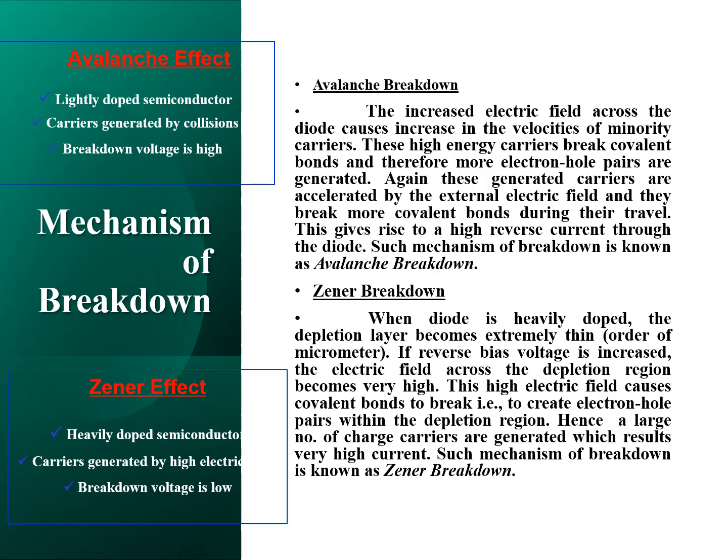In reverse bias, two types of breakdown occur: avalanche breakdown and Zener breakdown. What is avalanche breakdown? In reverse bias, whenever we increase the reverse voltage, the minority charge carriers gain higher energy and break from the covalent bonds.